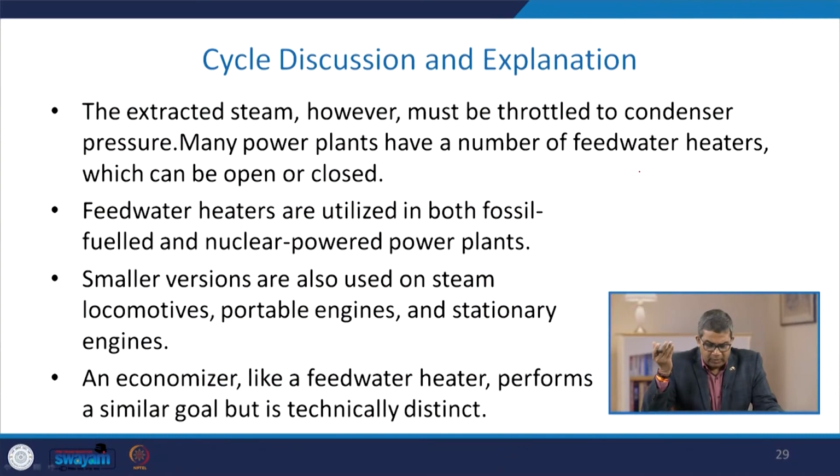The extracted steam, however, must be throttled to the condenser pressure, and many power plants have a number of feed water heaters which can be open or closed. The feed water heaters are utilized in both fossil fueled and nuclear powered plants. Small versions are also available, and they are used in steam locomotives, portable engines, stationary engines, etc.